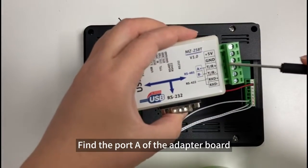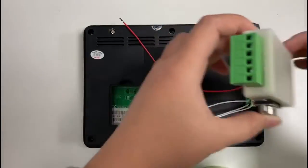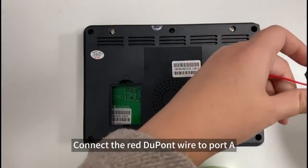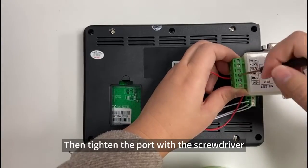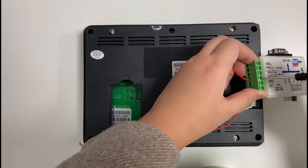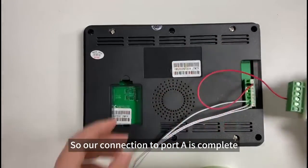Find the port A of the adapter board. Connect the red DuPont wire to port A. Then tighten the port with the screwdriver. So our connection to port A is complete.